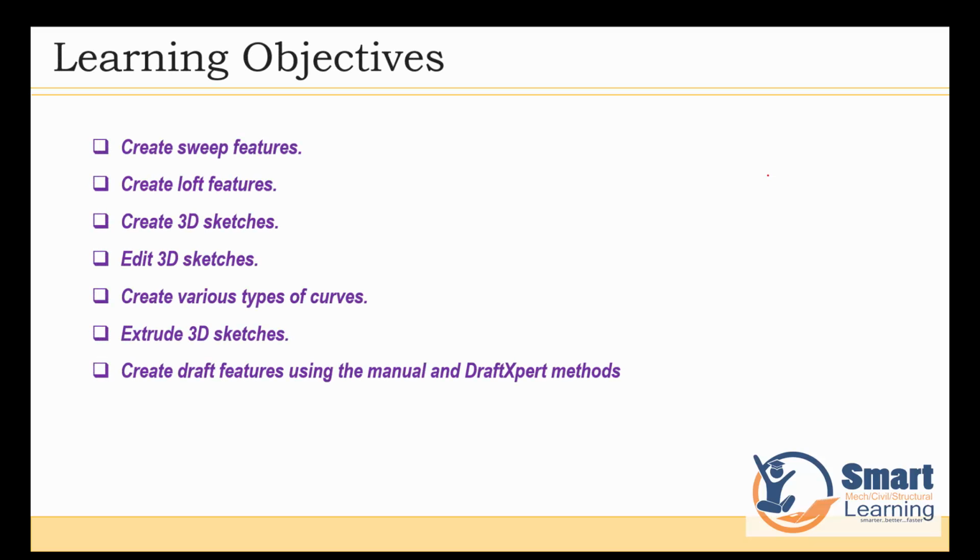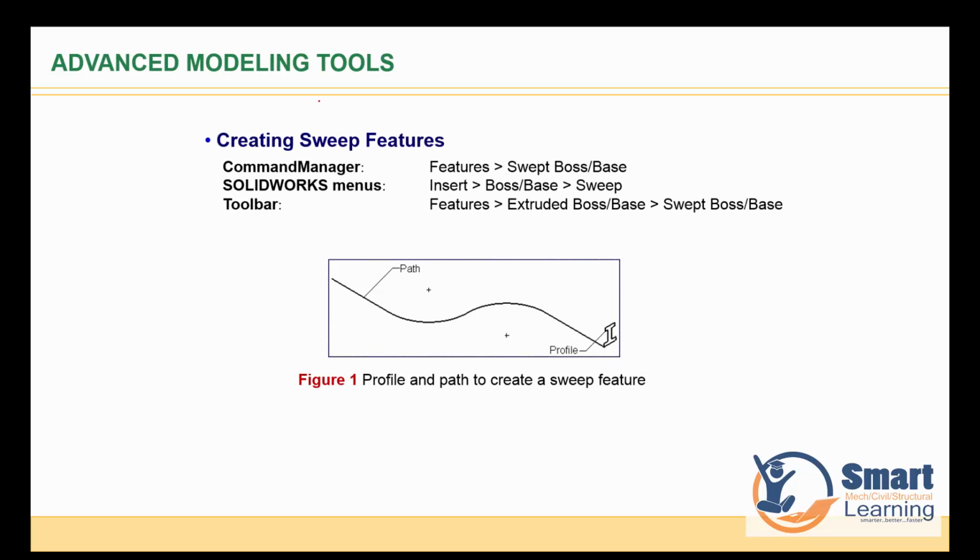We will understand how to create sweep features, and also we'll look at loft features, create 3D sketches, edit 3D sketches, create various types of curves, extrude 3D sketch, and create draft feature using manual and draft expert method. This is one of the advanced options which we'll also be discussing. And let us start with this particular concept under advanced modeling tools, creating sweep features.